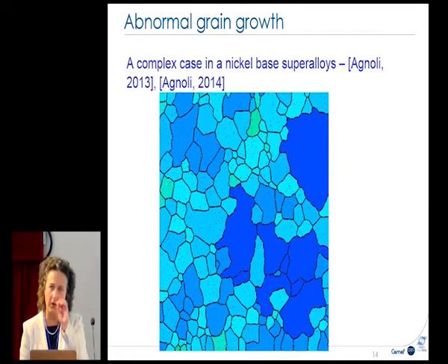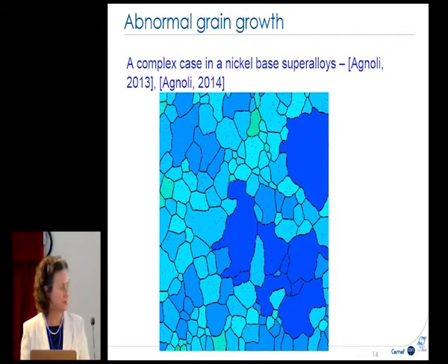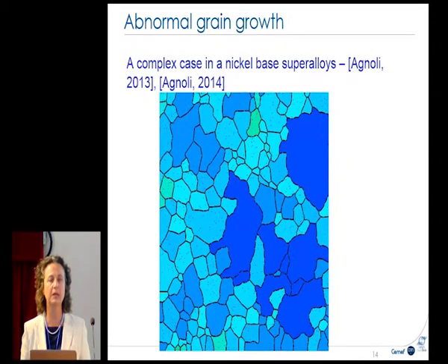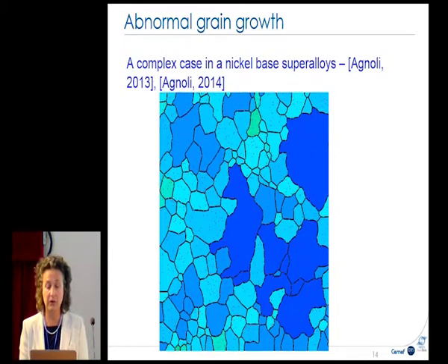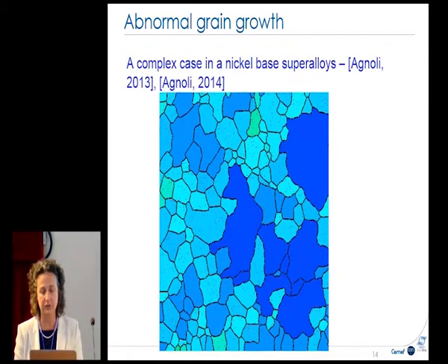Here are some very important features of this approach. It is very important to focus on the fact that we absolutely need automatic remeshing during the operation, because forming induces a large strain, so we need to remesh every time in order to follow the evolution of the material. So we have to solve this equation here.